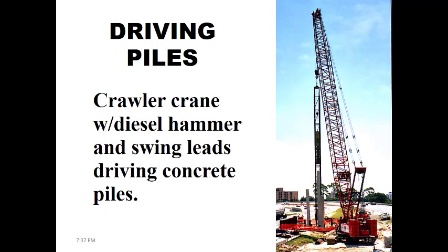If it breaks down, there is no way that you will be able to pull it out and then drive another pile. So in those situations, it might be necessary to do some structural change. It will require redesign for a localized solution in order to move the location of a pile.